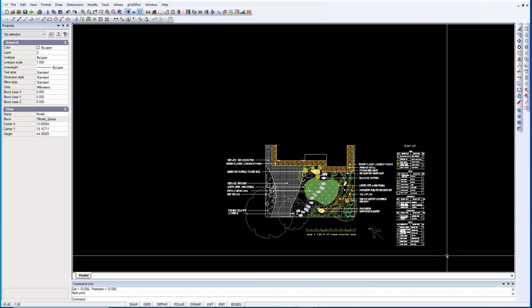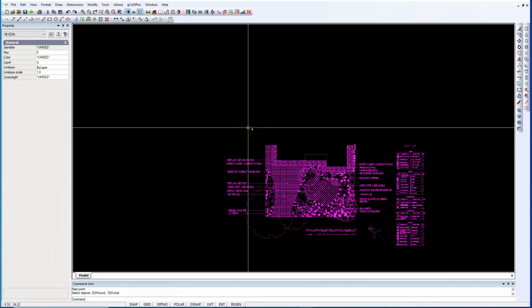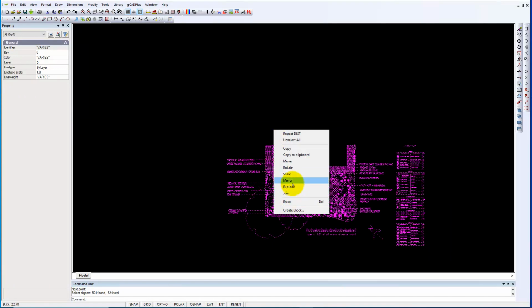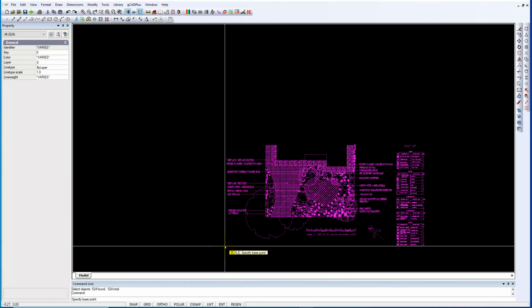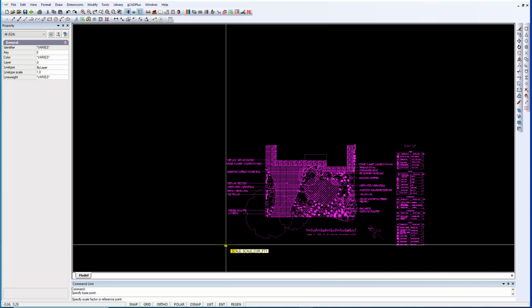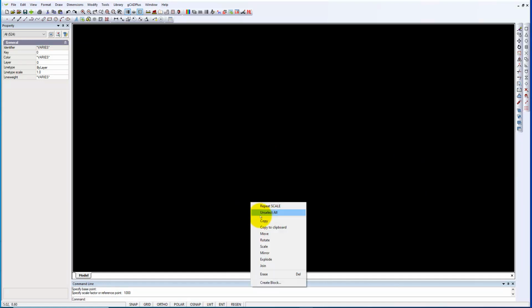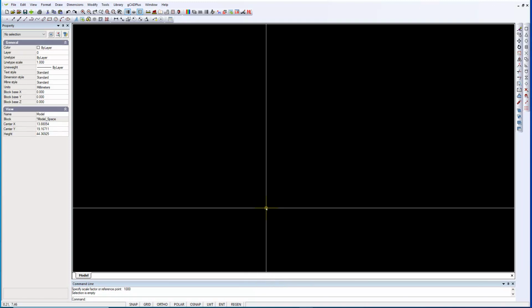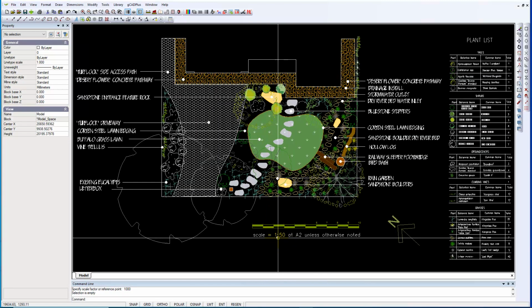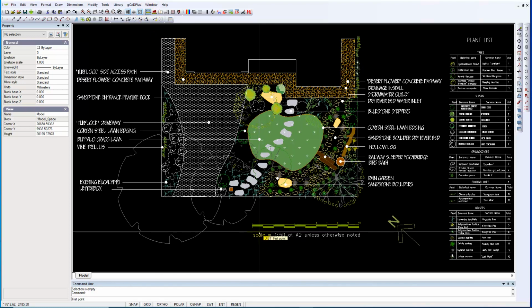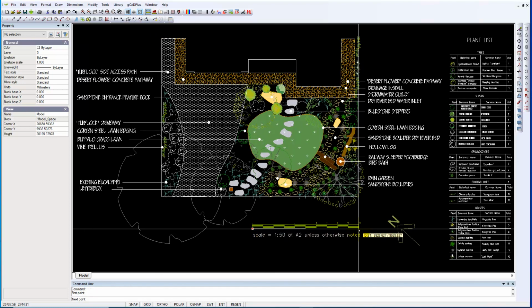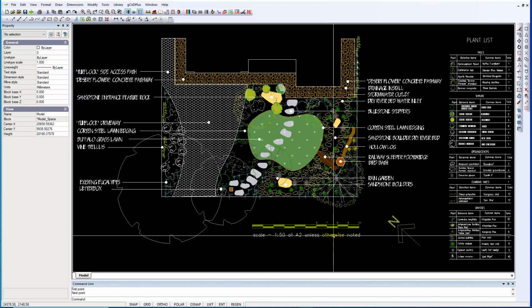a surveyor. So we can now select everything, right click and pick scale, nominate a base point. I'll just pick here, and then we'll type 1000 and hit enter. Things appear to disappear. It's a funny terminology. Unselect all, then zoom extents, and if we now use that distance tool again and move from one end of that scale bar to the other, we now have 10 millimeters. So everything in this drawing now is in millimeters.